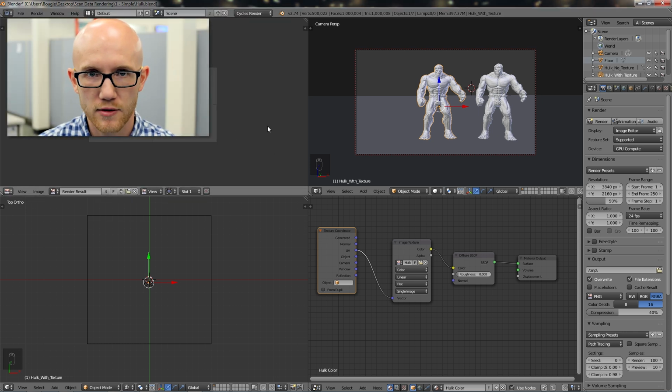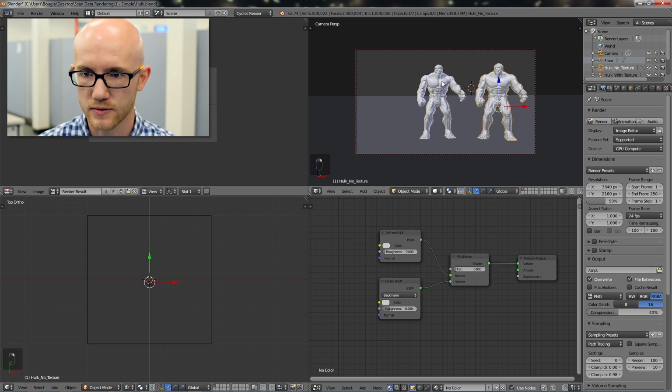So a couple things you got to remember in Blender. When you're selecting an object, you're actually right-clicking on it. I can select it here in this window here. If I just single-click, it's actually going to move what they call the 3D cursor. And that, I'm clicking around here in the bottom left window, that right here is where new objects will be placed when you import them into Blender.